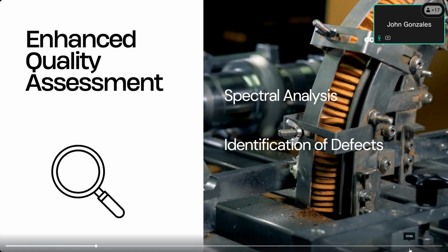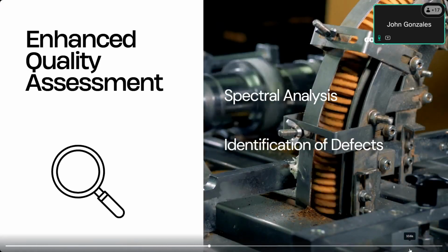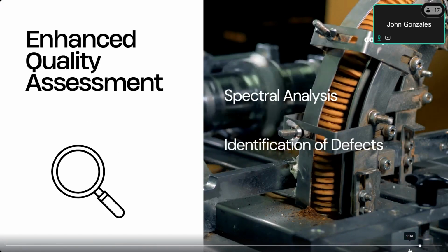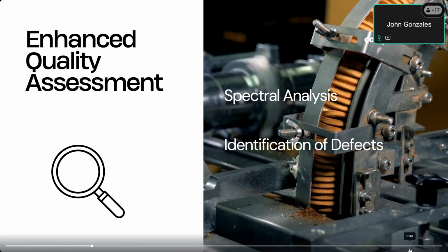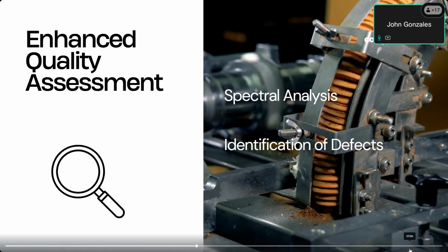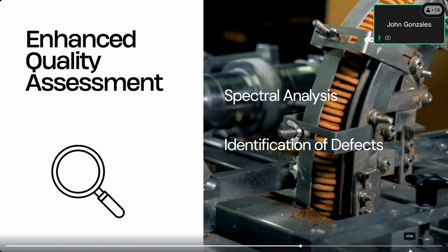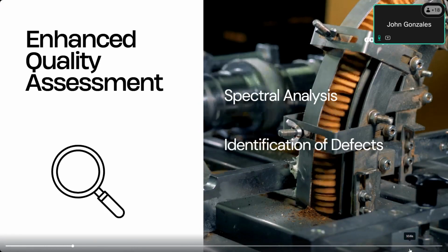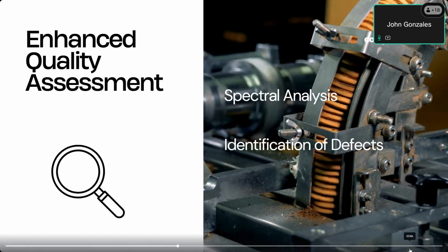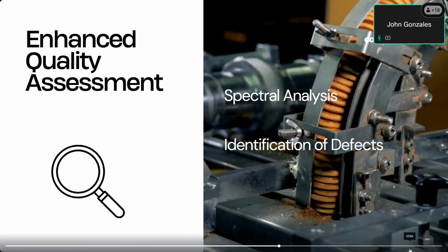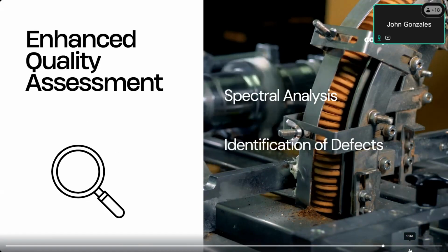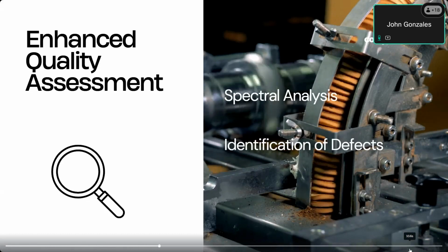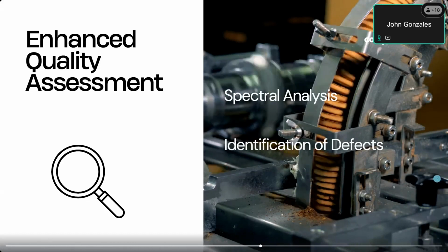Spectral analysis identifies characteristics like color, ripeness, and surface defects. It differentiates between healthy and defective items, such as bruised fruit and improperly sealed containers, by capturing specific wavelengths. This is essential because certain defects or contaminants are only visible or more easily detected under specific light and wavelengths, undetectable by the human eye. For example, a particular wavelength may highlight a bruise or reveal foreign material on the substrate.